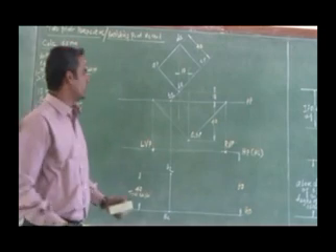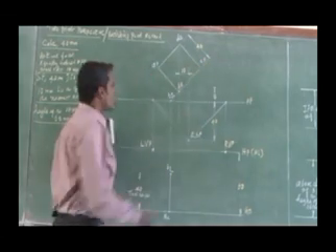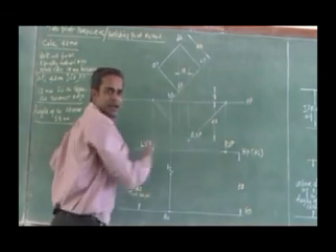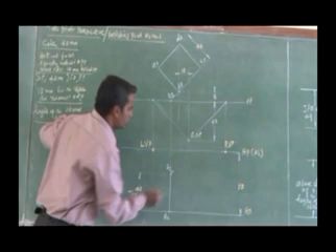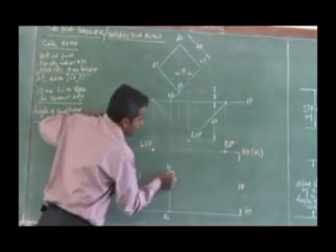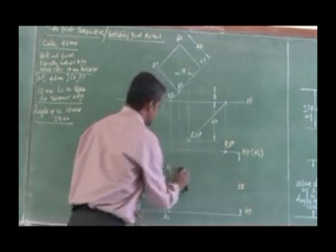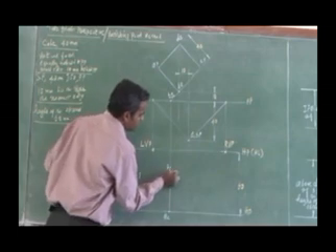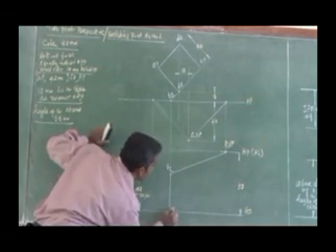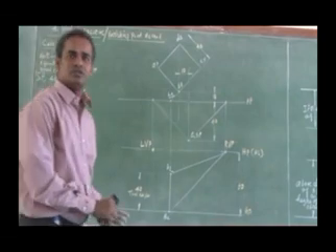Now to get the perspective location of the BQ edge and CR edge. In which direction have I extended? To the right vanishing point. So this B2 Q2, I am going to join to the right vanishing point with two vanishing lines. This is a vanishing line corresponding to Q2, and this is a vanishing line corresponding to B2.